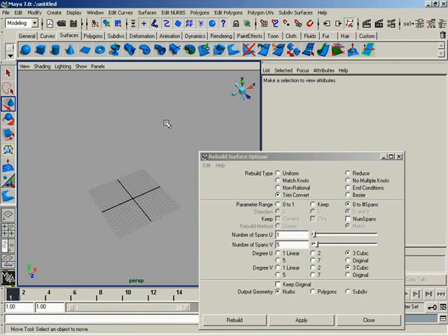It'd be a lot easier if that trim was a real legitimate NURBS surface. Don't get too excited just yet, because this rebuild type only works in certain situations. And by that, I mean only in situations where a NURBS surface would be possible.